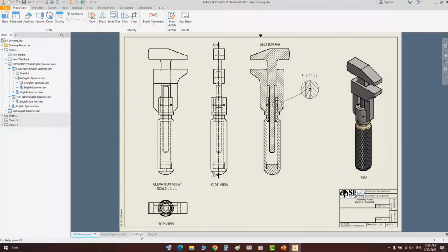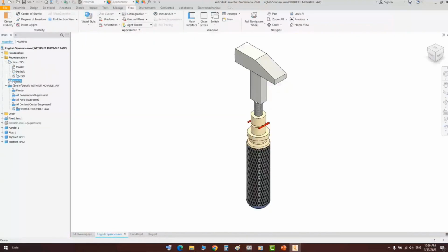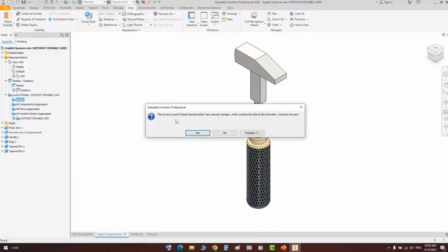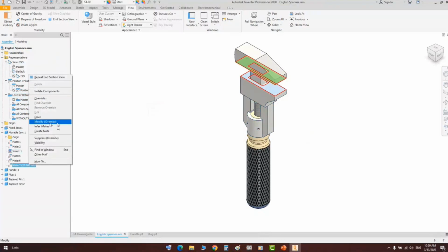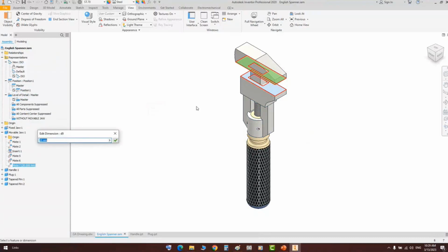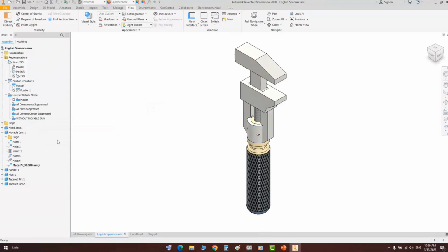And for the assembly itself here, as discussed, for the position, you can define a new position, which defines another position for the jaw. So let's make this position appear here, and inside this position we can define another value for modify and override. So we can make it 30 millimeters.